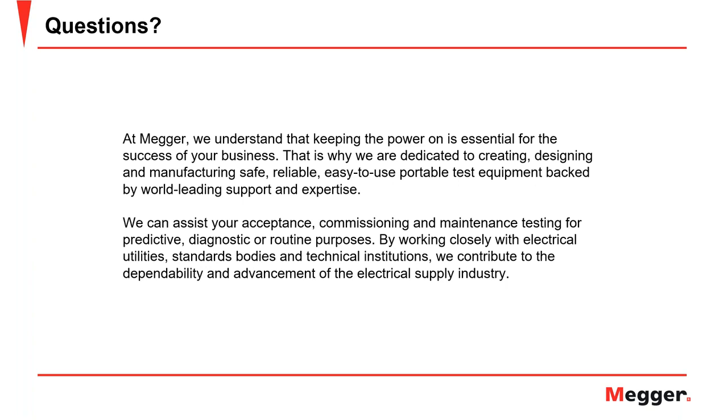because when you needed accurate control of speed and torque of a machine, you went to DC machines. AC machines are a lot tougher, stronger, and easier, but they were very hard to control when it came to proper control of the speed and the torque of the machine. But that all changed in the 80s with the introduction of vector control, and then in the 90s when that went mainstream.